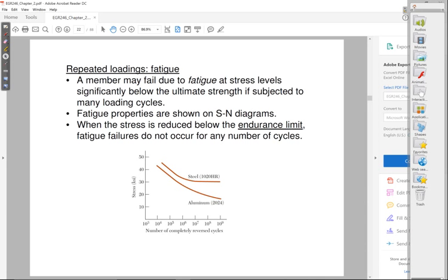And you might think that as long as that stress is less than the yield stress and definitely less than the ultimate stress, then it's fine. You could use this drill bit forever without it breaking. But what people found is that after a certain number of cycles, actually, pieces did break. Things did start to break. Okay, so this is what's referred to as fatigue.